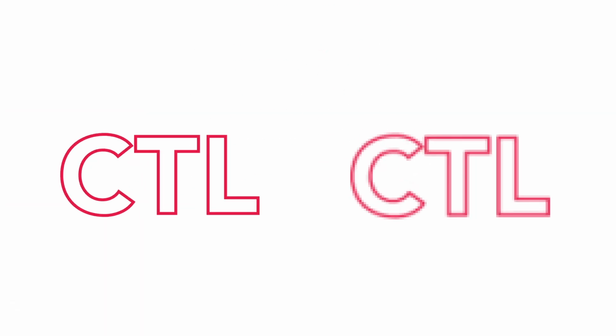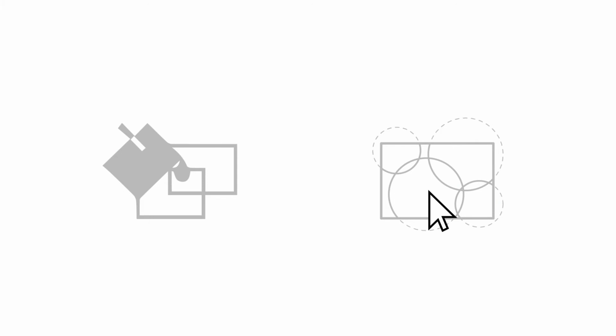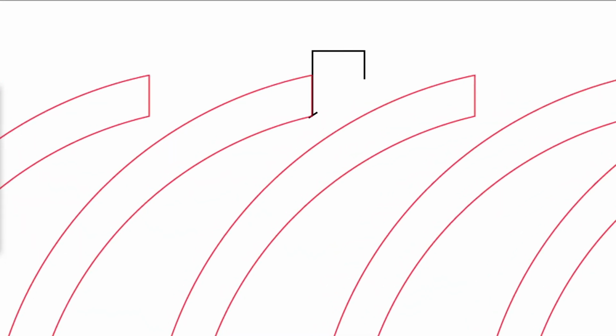As a general guideline, make sure all lines are vectorized or converted to curves. Turn off all live paint or clipping mask functions. Nest any repetitive cutting components to conserve material, allowing at least 2 millimeters between each shape.